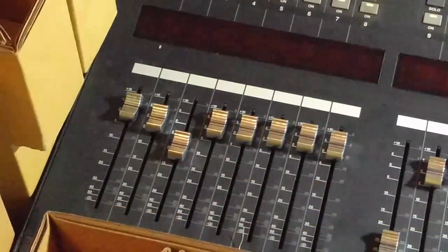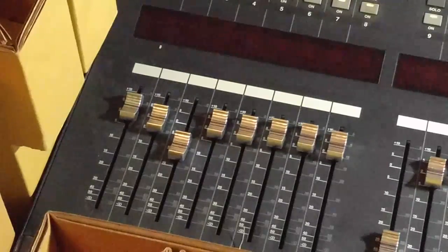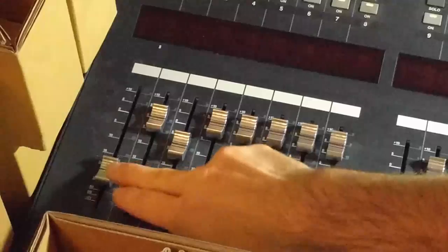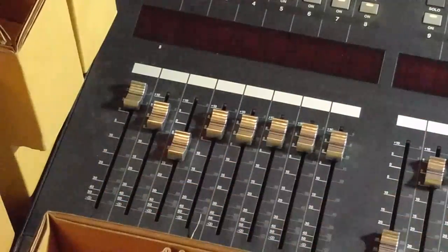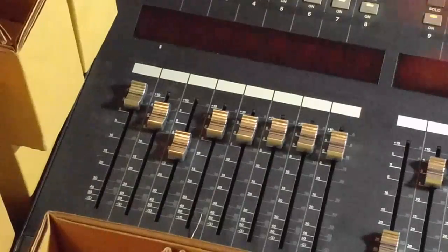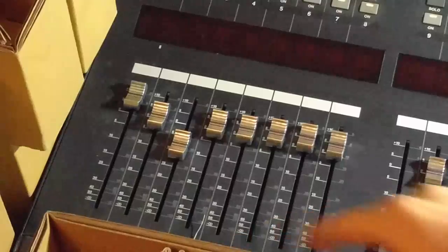It's taking the analog information of the fader, because you're still working with analog audio here, and converting that digitally. So when the fader is mechanically gunked up so that the analog tracks of that wiper are not producing a constant and complete resistance, that goes from 0 to 100K, let's say, probably something like that. If it's only measuring 0 to 90K, or if it's jumping around in resistance when it gets to that bad spot, which is right around here, as it's letting me know, that's when you have that symptom. It's the same symptom I had in the Control 24.